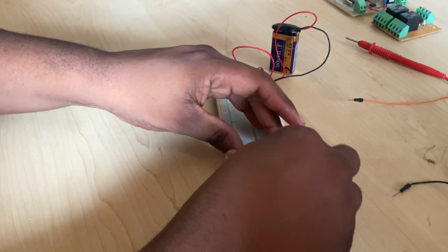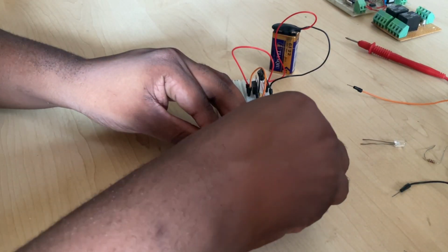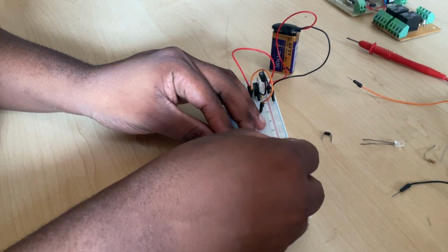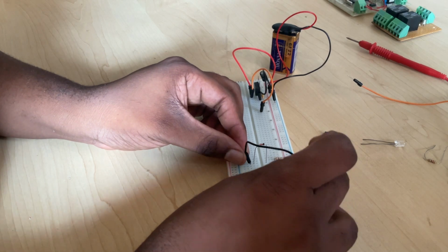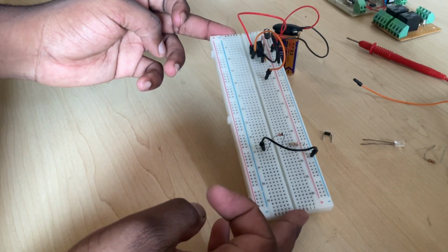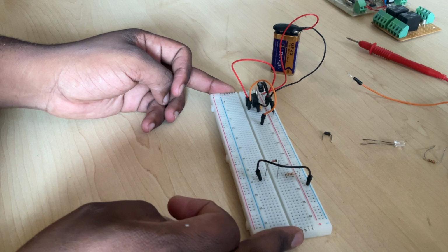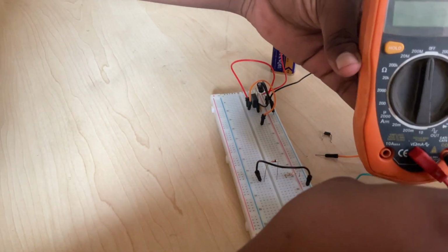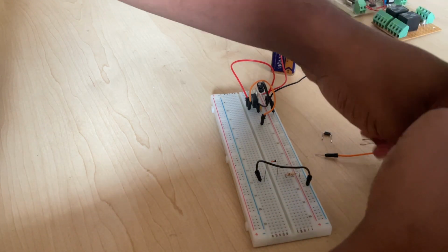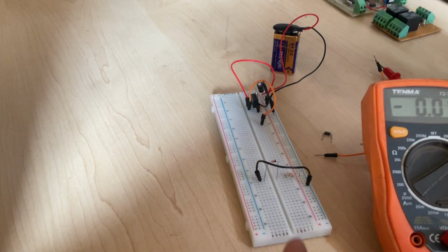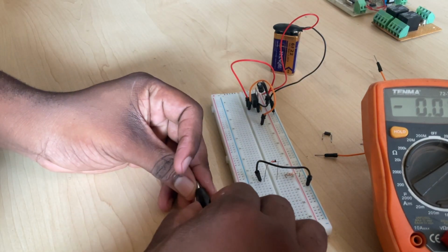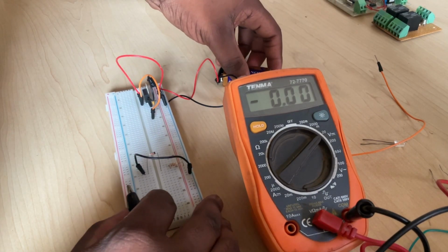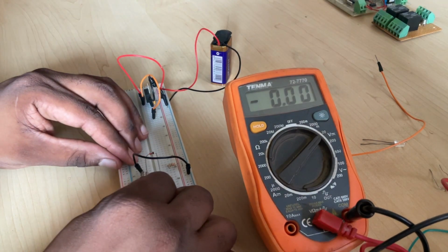The third circuit we're going to build is a voltage regulator using a Zener diode. And this is how it looks. If you remember, with a Zener diode, it's going to allow current to flow in the opposite direction only if a certain voltage is reached. So for this specific Zener diode, the reverse breakdown voltage is 5.1 volts. We are going to use a multimeter to measure the voltage across the diode.